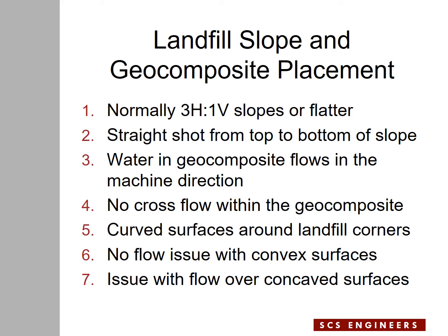But if the geometry of the landfill footprint is such that you end up with a concave surface, the geocomposite role becomes a very important matter in the design of the drainage layer for the final cover system. And the drainage layer geocomposite sand may be in the same category as well. On concave surfaces is the subject of this presentation.